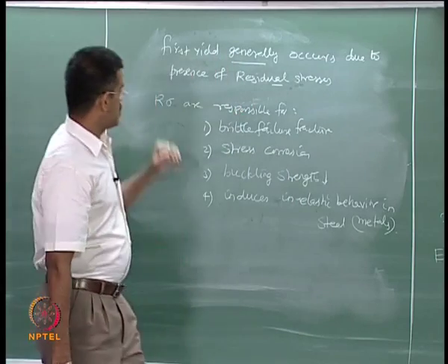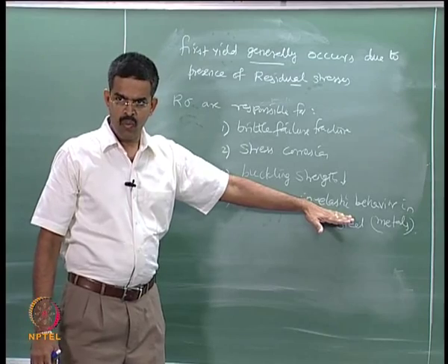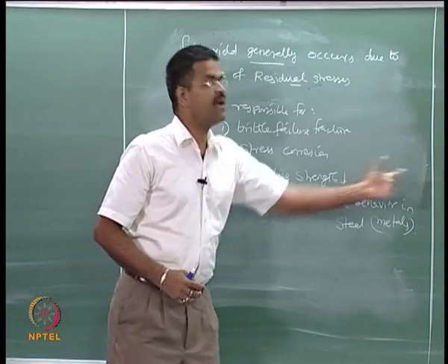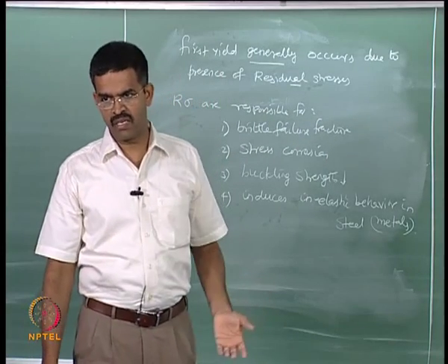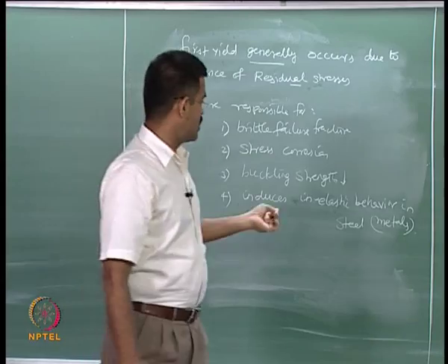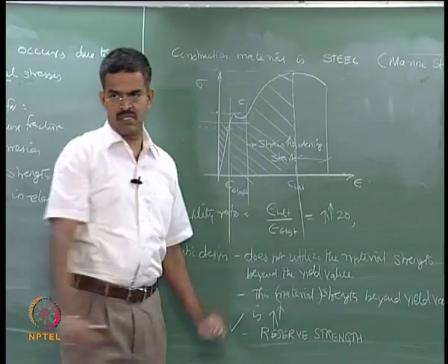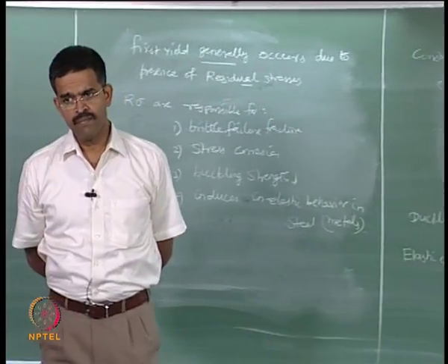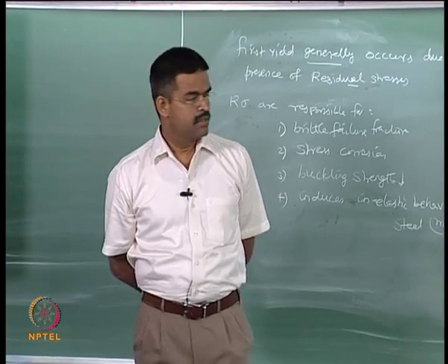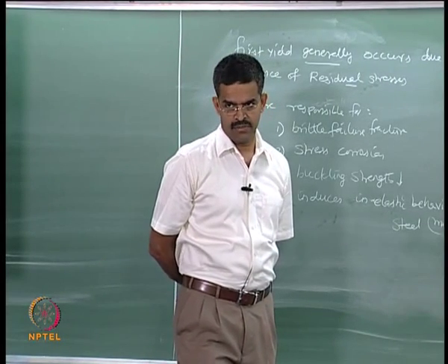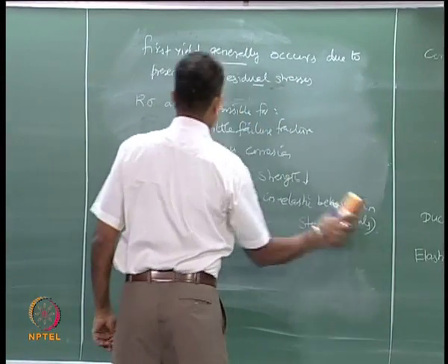Okay. Residual stresses cannot be avoided, they initiate an inelastic behavior. Why can't I use this as an advantage in my design? That is what I am looking for as a justification for my plastic design, because plastic design accounts for the reserve strength which is in the inelastic zone. Okay. So, people said, okay, let me explore the possibility of design beyond the so-called elastic limit. Is that clear? So, let us remove this.